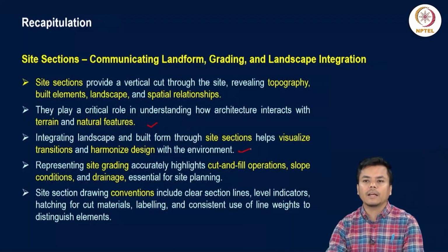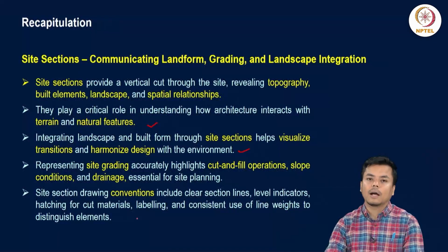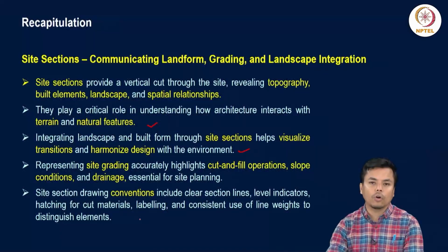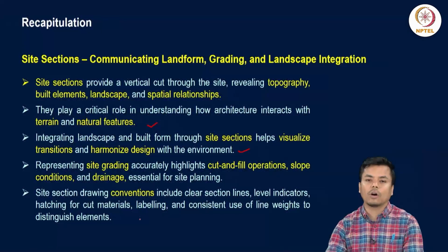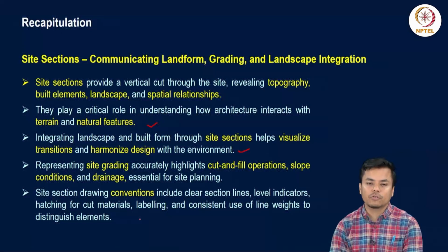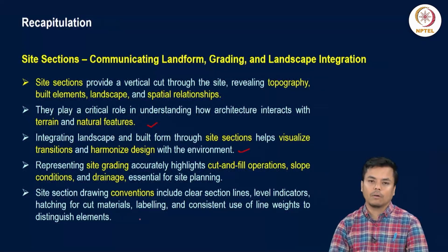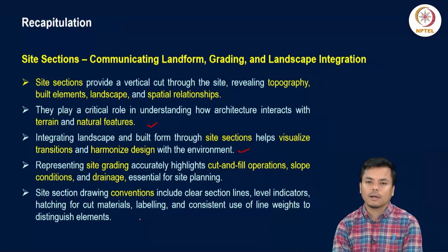Representing site grading accurately highlights cut and fill operations, slope conditions, and drainage, which is essential for site planning. Site section drawing convention includes clear section lines, level indicators, and hatching for cut materials. These are some important instructions that have to be followed when you showcase a site section, or else it will create confusion to the person who will be looking into your sheets.